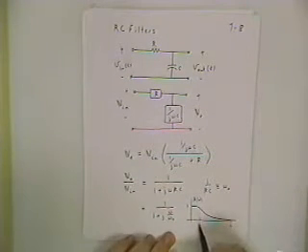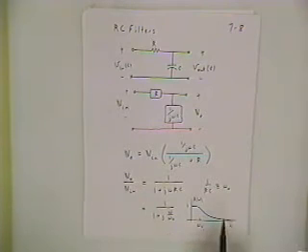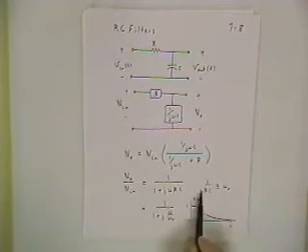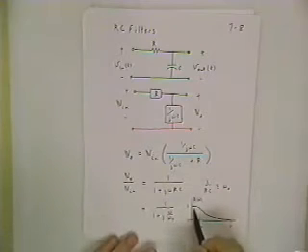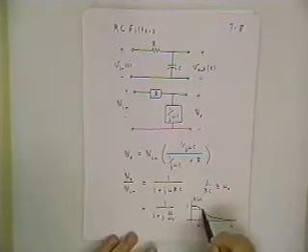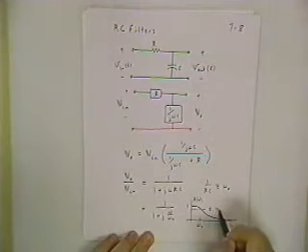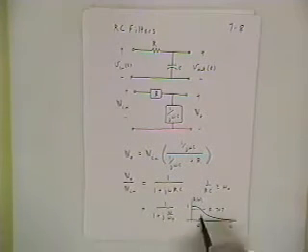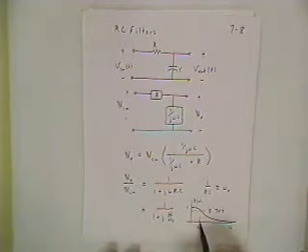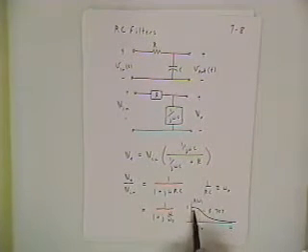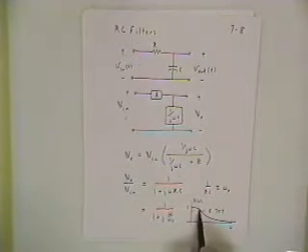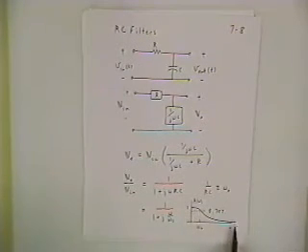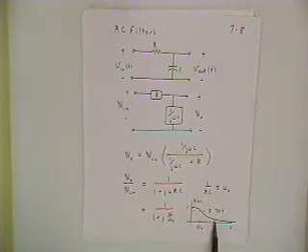Omega naught is the value right here, and just from the way we've defined it, it happens to be the point where this amplitude goes down to 1 over square root of 2 of its original value, its DC value. So this gives you an interpretation of this omega naught. It's called the corner frequency because this is roughly where the curve starts to turn around the corner of decreasing amplitude with increasing frequency. But what we have here is a pretty close match to the low-pass ideal.